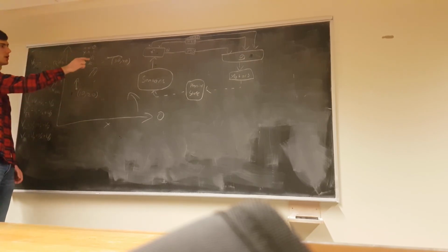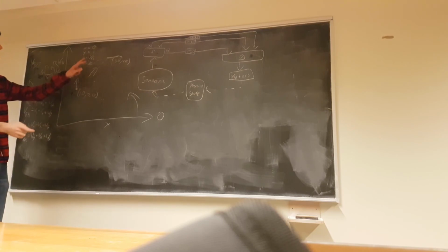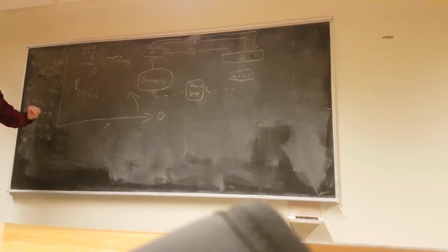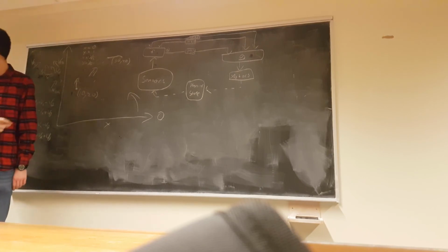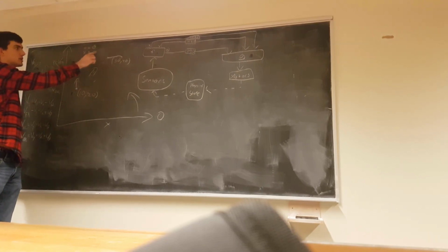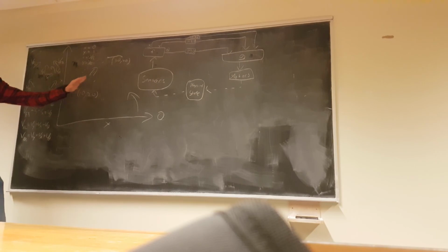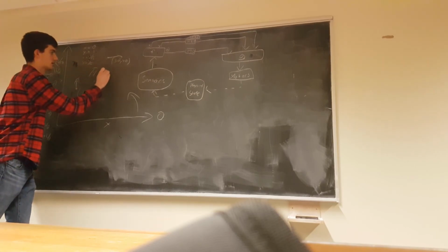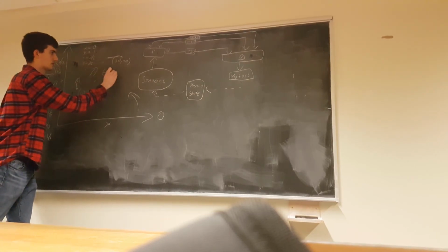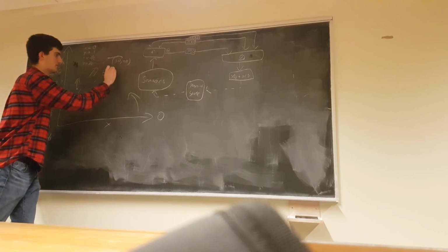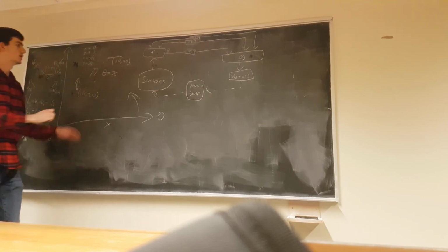So you rotate it by a positive value of theta. You get, basically, this telling you to go equal amounts left and forward. If this went equal amounts left and forward, which way would it move? Vector x equals 0, y equals 1, rotated by theta, where the direction the robot's facing is pi over 4.